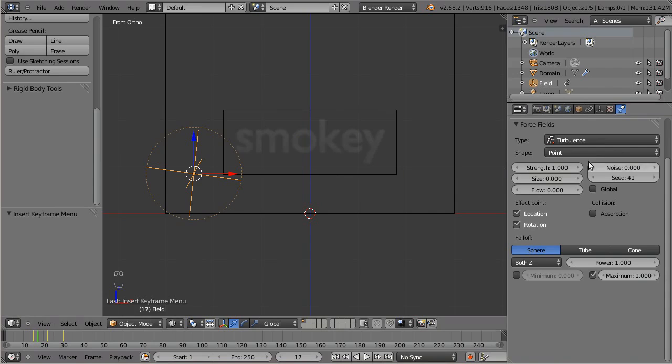Okay, to make this have an effect, you need to add some flow force, like 10, and this will convert the force into an airflow, which you will need to be able to move the smoke. And now the strength is really low. It's going so fast that we need a really high strength, like something like 600. A really aggressive force that moves really quickly. And because it's just here for such a small time, it needs this really high force.